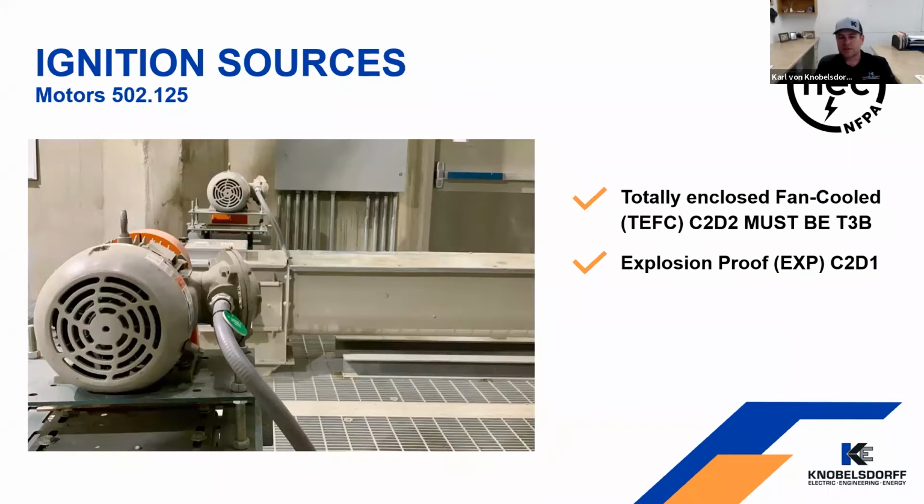So now we'll get into the different types of ignition sources that we're looking at when we're rating equipment that can be installed in an area. So once we've identified the class of material that we're dealing with, if it's class 1 or 2, and then the division of the location, if it's a division 1 or division 2, now we have sections of the code that tell us the materials, what they have to be listed for, and what materials we can use in each one of those locations.